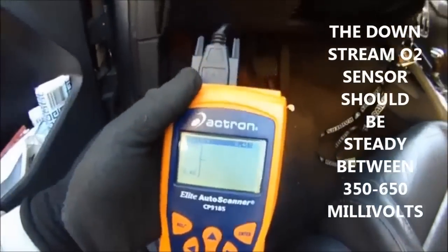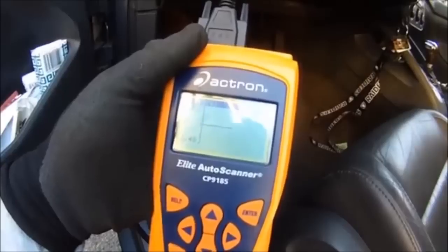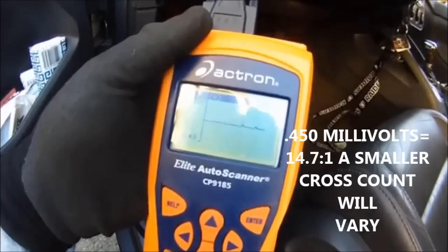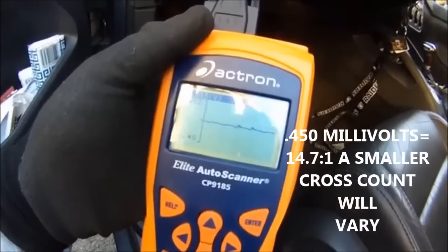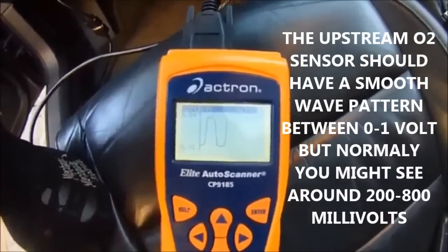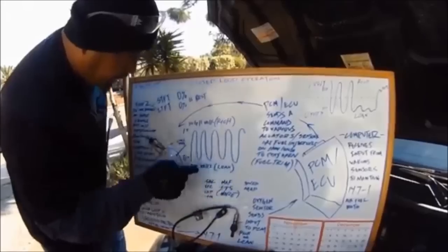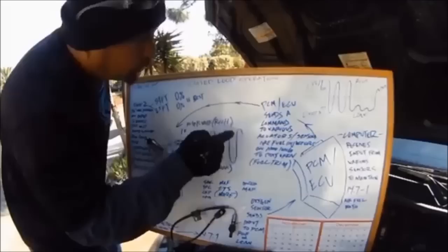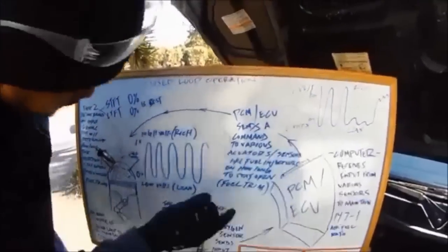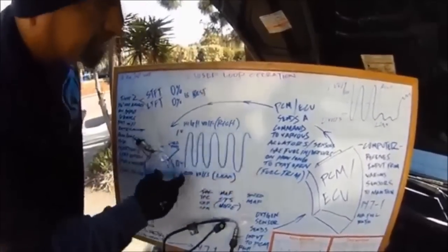This is an example of the secondary oxygen sensor, the one behind the catalytic converter. The secondary oxygen sensor should be at 0.45, right in the center, between 0 and 1 volt. This is the one in front of the catalytic converter, okay? You got 2 of them on most vehicles. One in front of the cat and one behind the cat. If you're up here, you're running rich, like this. If you're down here, you're running lean. So low voltage is a lean condition. High voltage is a rich condition.